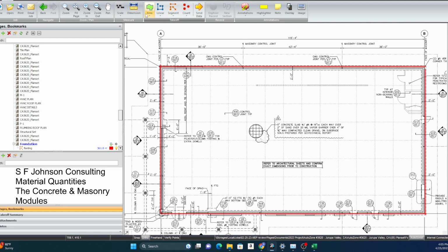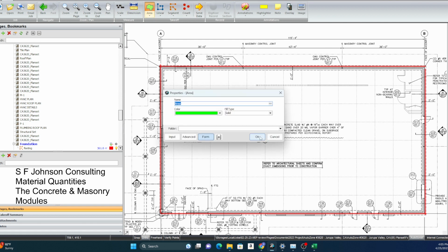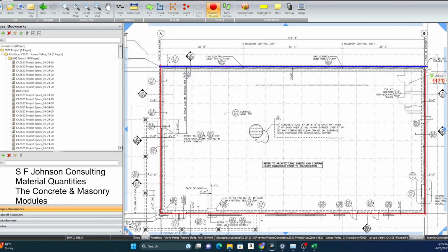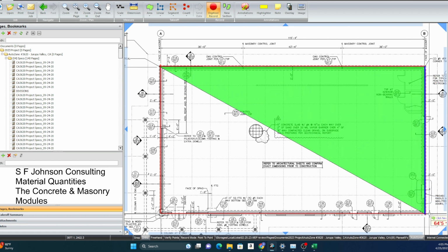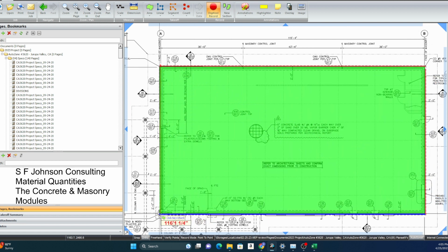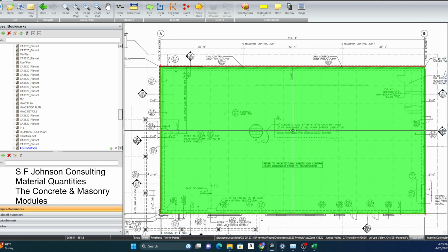And so first off, we're going to just figure out what our area is, and we're going to pretend that it's a 6-inch. Makes it easy for us. All right, so we have just about 7,500 square feet of concrete. Okay, so concrete, we always need those 3 dimensions, right? So the area is 2, the thickness is the third.